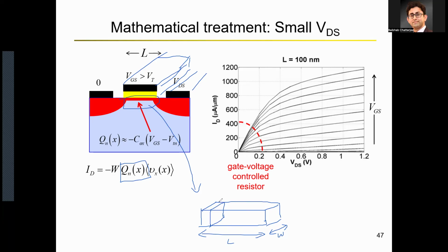You have to make area equal to the unit amount of W and L. So for that, you will have Qn times W. So the total amount of charge present in this cross section, remember, for this cross section the length is very close to 0 because it's just a section on this bar, but the width is still equal to W. The amount of charge present in unit area was Qn. So the amount of charge that would be present in this cross section would be W times Qn.